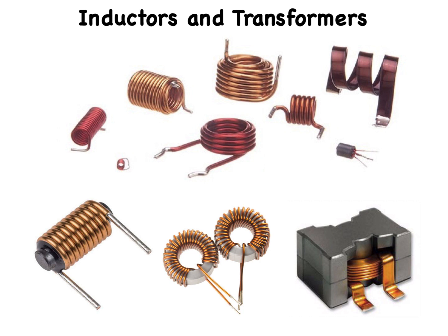Inductance is the property that opposes change in existing current. It acts in practice only while current increases or decreases. Coils or inductors can range in physical size from microscopic to gigantic, depending upon the inductance value of the component, and on the amount of current that it can handle.